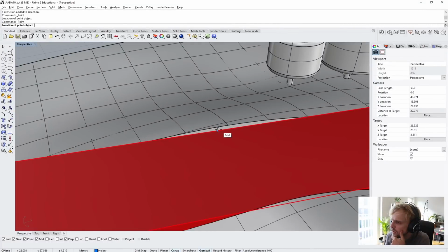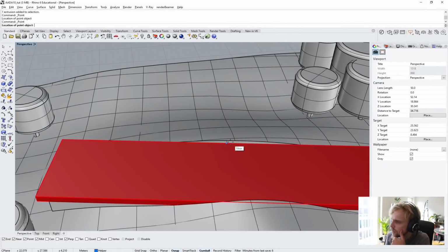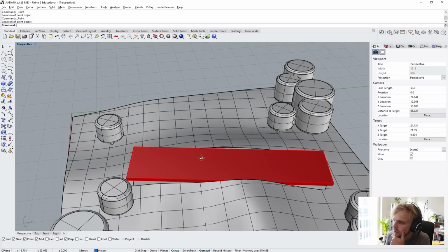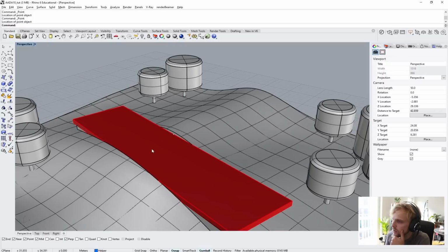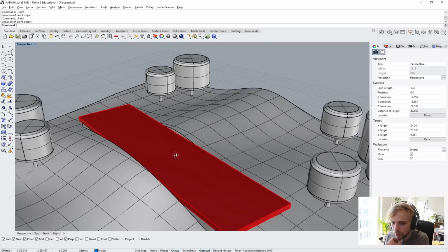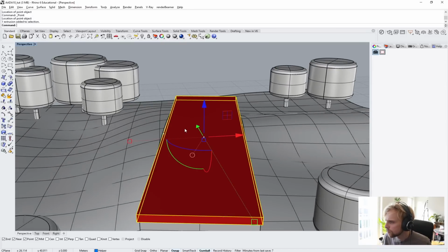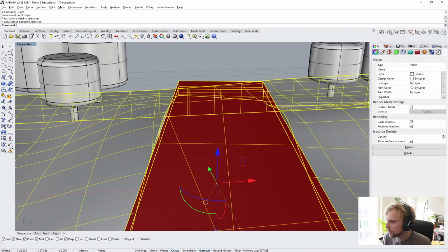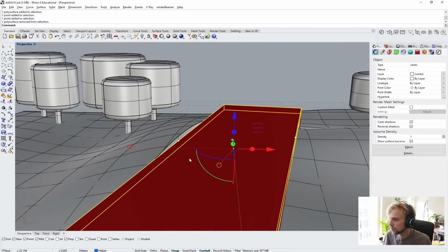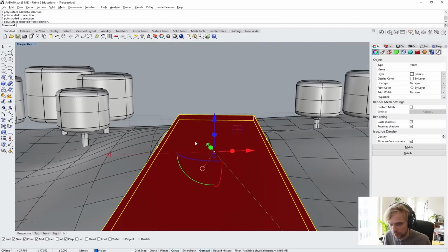And also kind of here, maybe. Oh, this is right in the middle. Yeah, sure. I'll add 1 point there, right? So it's going to be this walk-through pavilion. I think that's going to be quite nice. Okay, let me now select the box, select the 2 points, holding down the shift key. I accidentally selected the landscape as well, so to remove it from selection, I'll just hold down the control key and click on it. So now I do have my floor slab and my points selected.